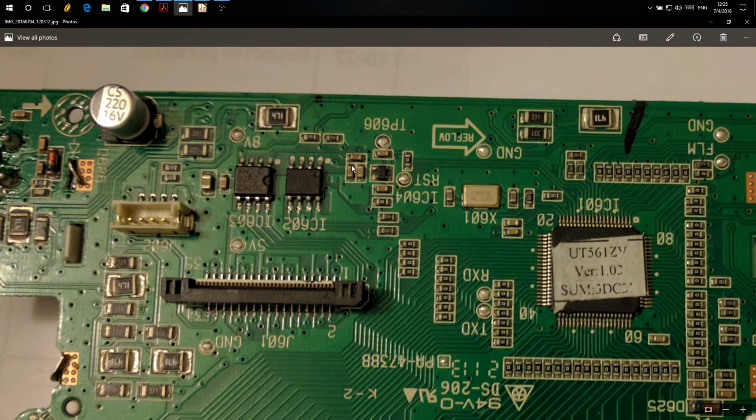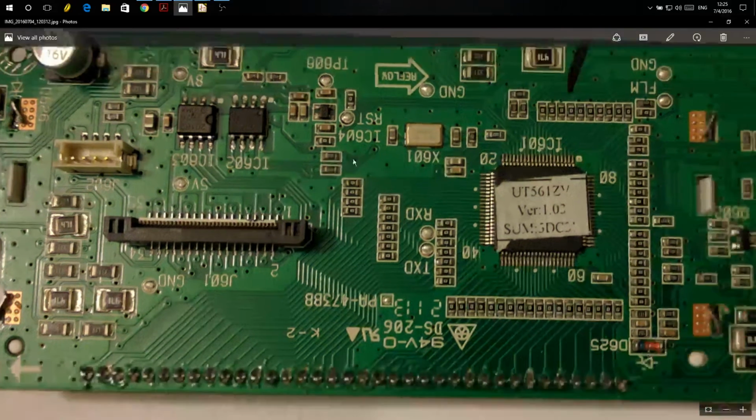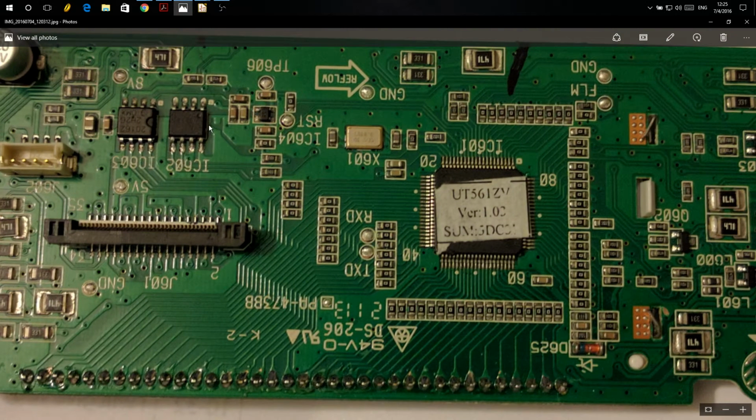There's not a whole lot to be gleaned in that EEPROM. It's not very big and it doesn't store very much. What I can tell you, however, is that this thing has a sort of freak out mode, more like a preventive measure, basically to prevent you from screwing around with it very much, where it'll overwrite all the data in the EEPROM and then it won't boot. So yeah, it works fine with a blank EEPROM, which is interesting.